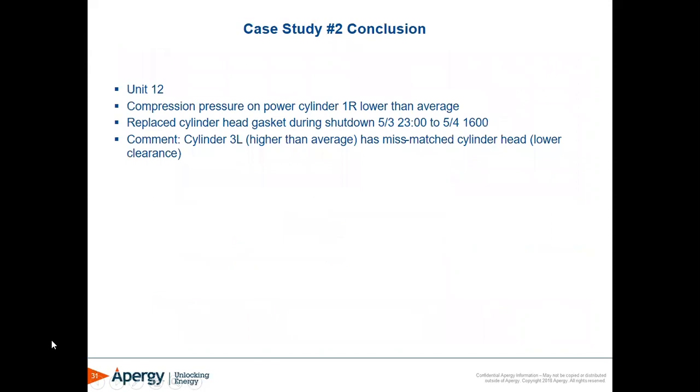In conclusion, compression pressure on power cylinder 1R was lower than average. Replace the cylinder head gasket during the shutdown. Then one thing to comment on is just that mismatched cylinder head.